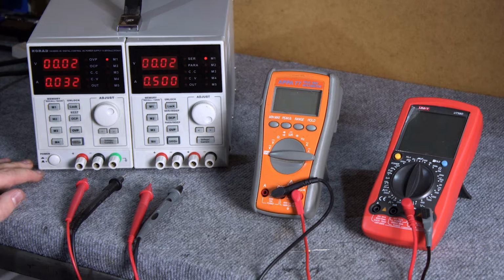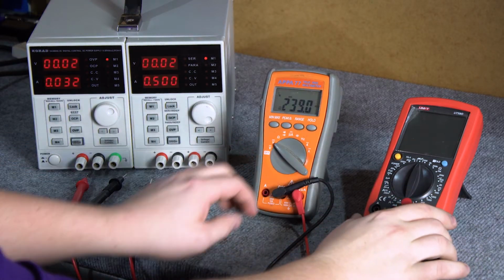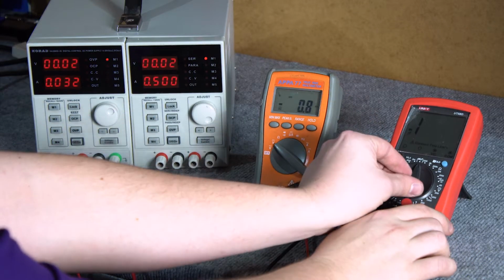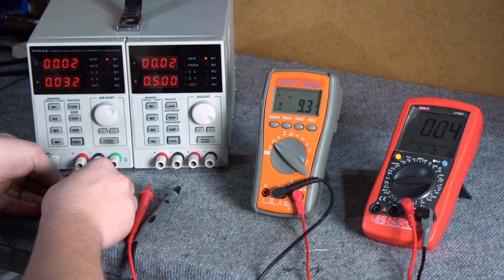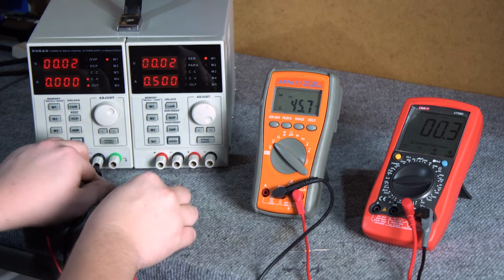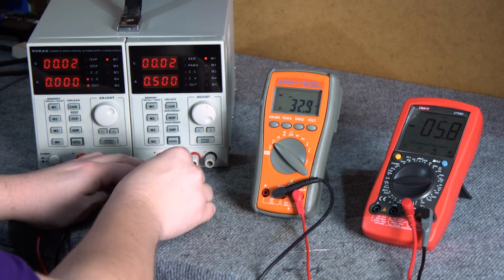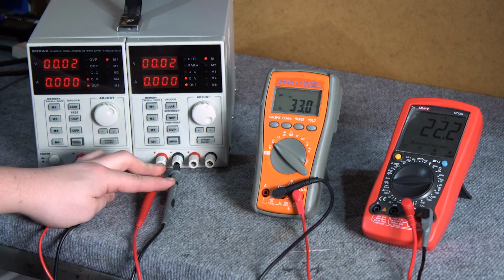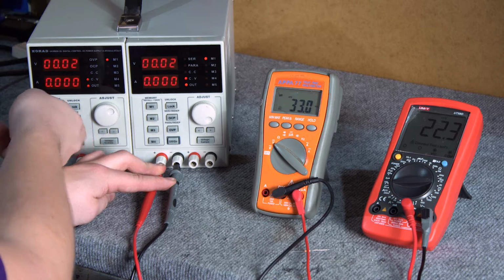When, for example, we measure voltages of 1–2 volts, we can set the appropriate nearest range. However, when the voltage increases, the display will show that we have exceeded it and it should be set to a higher one. One could ask why we do not use only the highest range. Each meter has its measurement error determined as a percentage of the given range, plus minus error of the last digit.